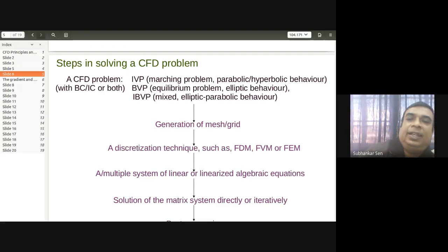That is discretization. So by generation of mesh or grid, what do we do? A domain which is a continuous domain, now we divide into small segments, into small subdomains. By generating small subdomains, we introduce many nodal points where the grid lines intersect. At those nodal points, we write the approximate equations and we solve these equations.